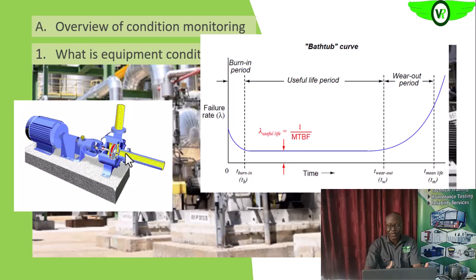Then the discharge pressure. So as you go out to take your bearing temperature, you record, you log. As you are logging, if everything is normal, you have that normal temperature over time. But as the equipment starts deteriorating, the bearing temperature will start going up. Even the vibration you are monitoring will start going up, which means that the probability of failure is already increasing.